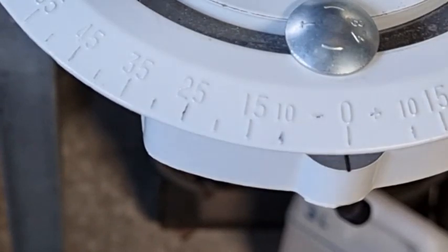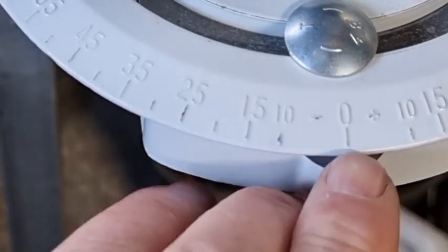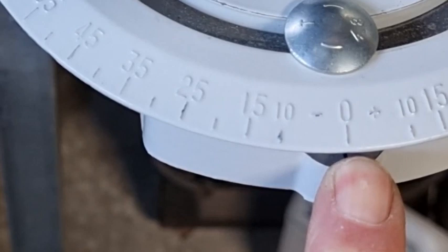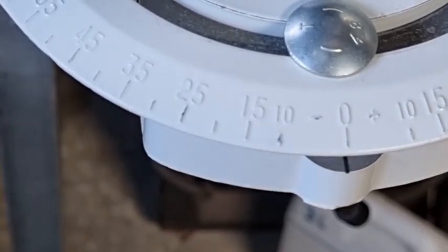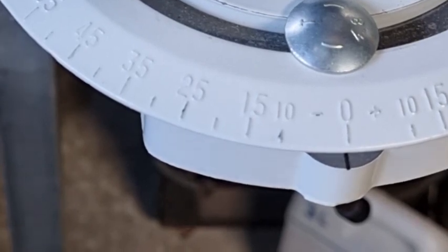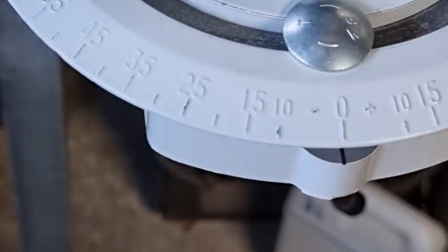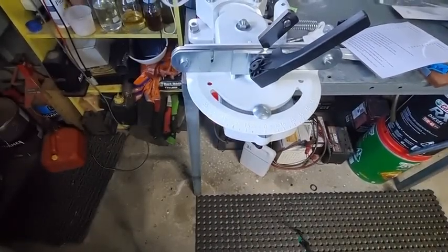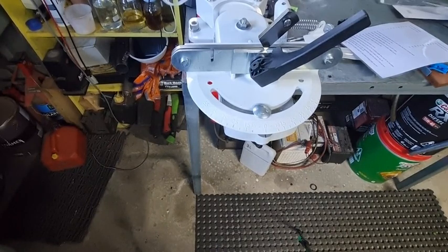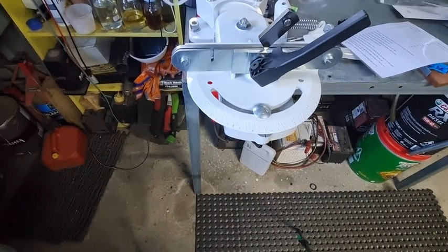You could have equally had 90 degrees on here, and then you would have moved it to 60 degrees left and right, which is exactly what the tooth angle is. But remember, as I said before, it's not a tooth angle we're referring to. We're referring to a file angle, which traditionally goes back before grinders were invented. So I hope that addresses the difference between Oregon type grinders and Stihl.